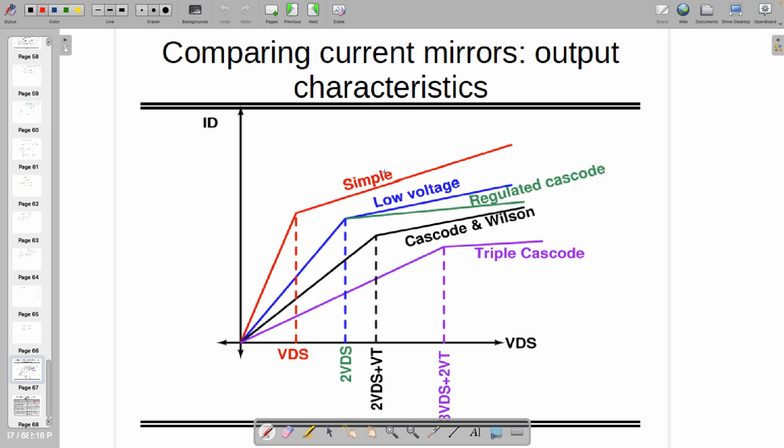So we started from the simple current mirror which we have drawn just now, whose VMIN value is VDS,sat, and you know the value of VDS,sat we should generally achieve is more than 250 millivolt. So ID versus VDS is going to give you, by the way, this is an approximate plot. The actual plot might look something like this. This is the IV characteristic only.